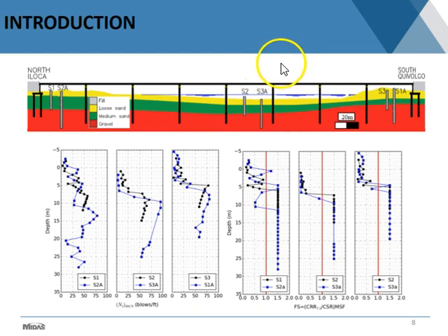And if you use the 0.4 g and you use, let's say, the latest Boulanger and Idriss liquefaction susceptibility plot using SPT, that is going to give you a high CSR value that is going to anticipate the occurrence of liquefaction for everything that has an SPT of, let's say, 28 or 27 blows per foot. I mean, any sandy material below that number, according to that procedure, was going to experience liquefaction.